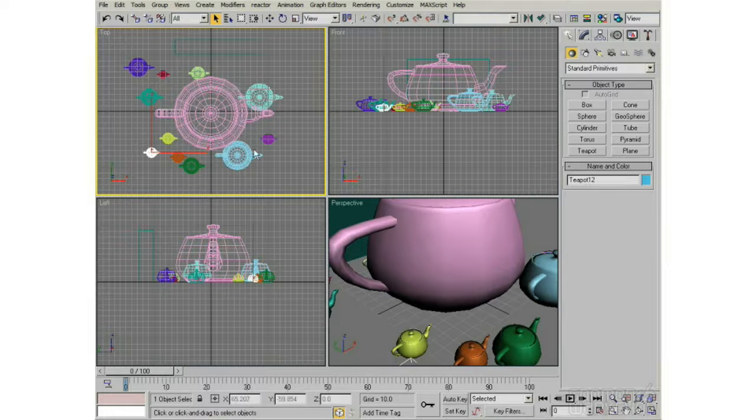So I can see it mostly in my ortho views, but in my perspective view, I'm not able to see everything. Now, that means we need to be able to manipulate those views. So this is something that you're going to do. It's the thing that you're going to do the most, is manipulating views. And so there's some hotkeys for it, and there's also some buttons for it. I'm going to tell you the hotkeys first, because that's what you're going to do 95% of the time at least, is use your hotkeys and your mouse buttons to manipulate views.